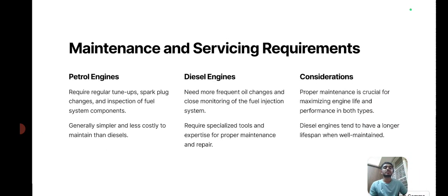Maintenance and servicing requirements. Petrol engines require regular tune-ups, spark plug changes, and inspection of fuel system components, and generally have simpler and less costly maintenance than diesel. Diesel engines need more frequent oil changes and close monitoring of the fuel injection system. They require specialized tools and expertise for proper maintenance and repair considerations. Proper maintenance is crucial for maximizing engine life and performance in both types. Diesel engines tend to have a longer lifespan if well maintained.